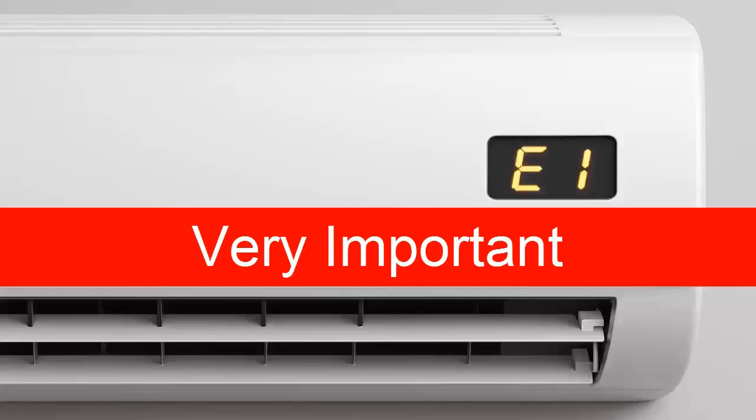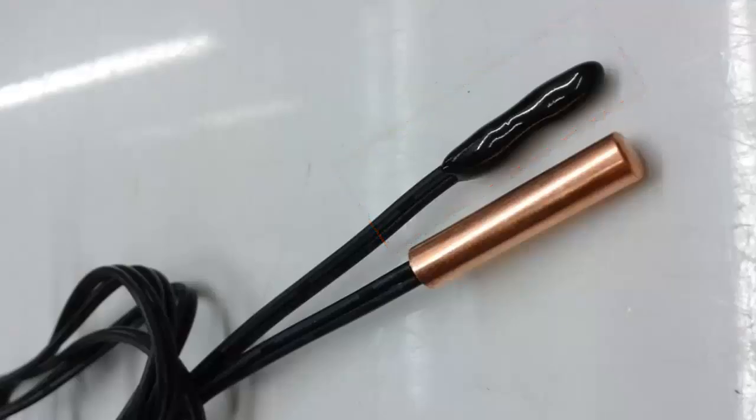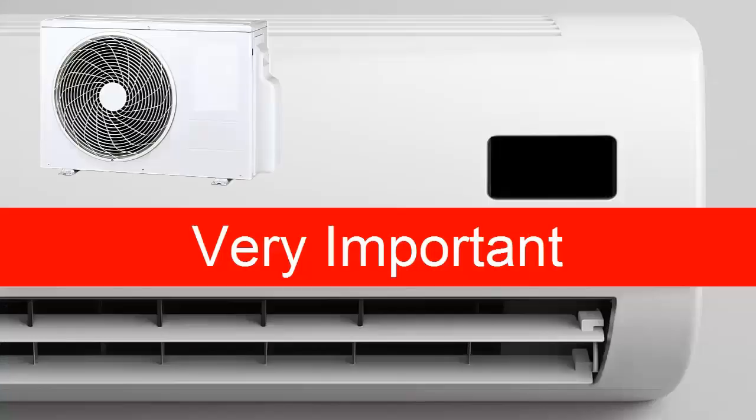If your unit's brand is not on our list, we recommend the following. If your unit is a conventional, non-inverter type, try the suggestions related to the indoor temperature sensor. If your unit is inverter-based, the error is more likely related to communication issues between the indoor and outdoor units. In this case, we suggest following the recommendations explained in the video.